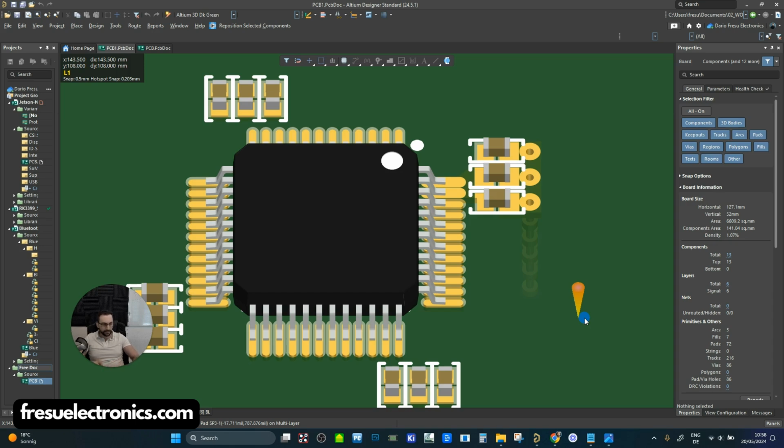And then based on this target impedance, we can calculate how many capacitors we need by a simple equation, which is basically twice the series inductance of the capacitor that we are choosing, divided by the target impedance times the time for the transient current required by the IC.